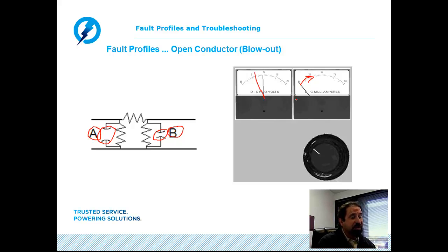It has also been noted on some occasions, when the ground is very dry and we have a blowout fault with a sizable burn back or gap on the source side, that the cable may actually support and sustain the applied voltage during the test and not flash over.